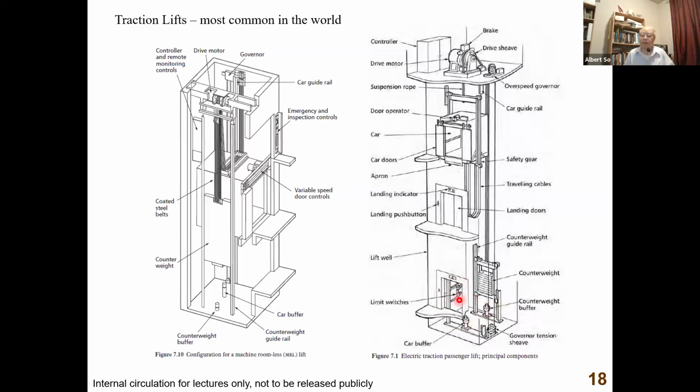At the bottom of the hoistway there is a lot of equipment. So if you fall down, let's say from 5 floors, down to the pit, even if you do not get killed, you're seriously injured, right? So this apron is to fill up the gap. Of course, if the car is far away from the landing and the landing doors are still open, there will be a hole there. It's very dangerous. But although there's no power, the landing doors can close themselves. It's mechanical, easy, passive.